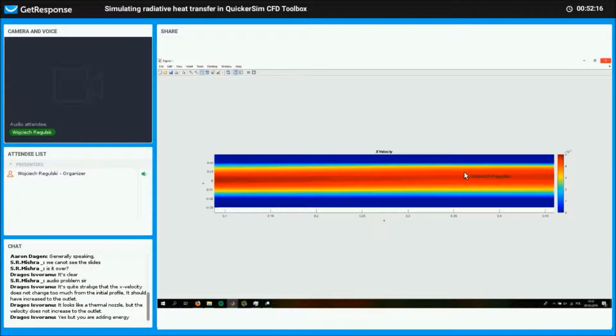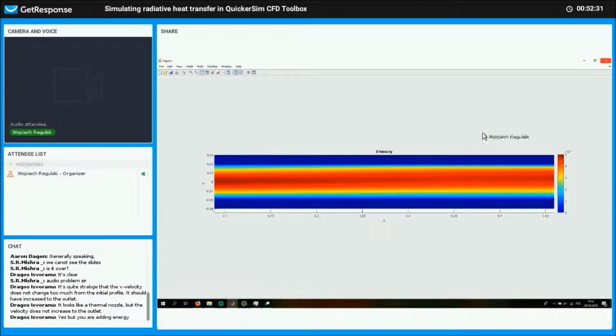The temperature field didn't really get far from the wall of the channel itself because the wall has high thermal conductivity, but water has low thermal conductivity. So as you saw in the viscosity field, the larger part of the channel still had the initial viscosity based on the temperature.